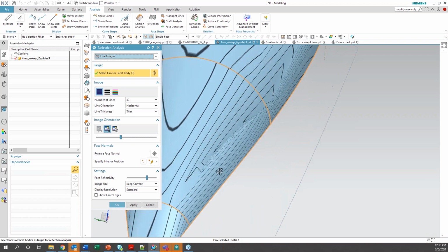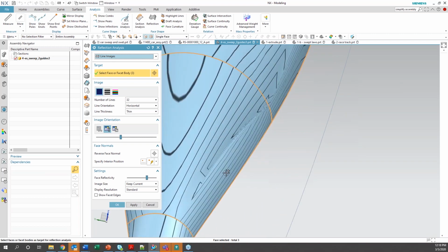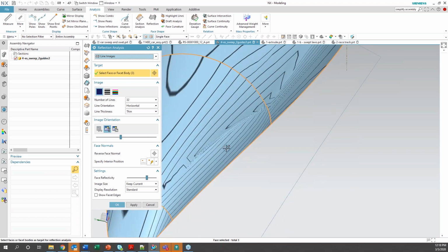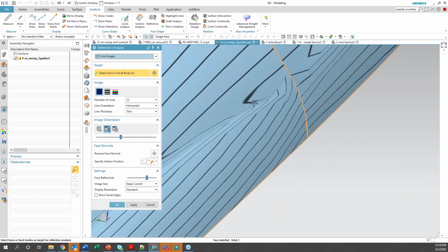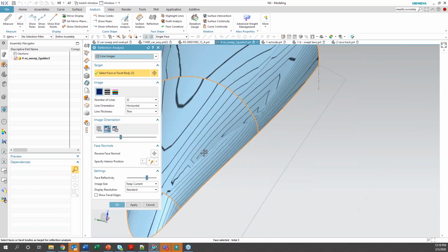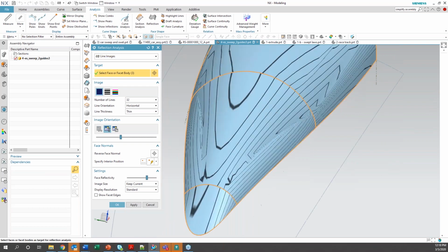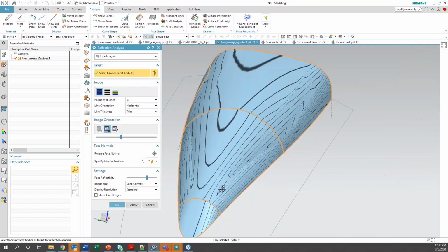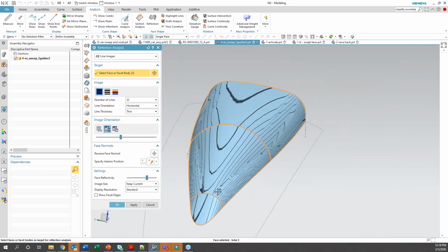You could see where the lines, the reflection, it's like holding a flashlight or a mirror, that this would be a mirror. You could see that you wouldn't look too good if that was your face in the mirror, right? It would distort it here. So we're trying to get smoother lines. Where it breaks but still touches, it's a discontinuity in curvature. Where it breaks and doesn't touch, it's a discontinuity in tangency as well. So we're going to try to fix that.